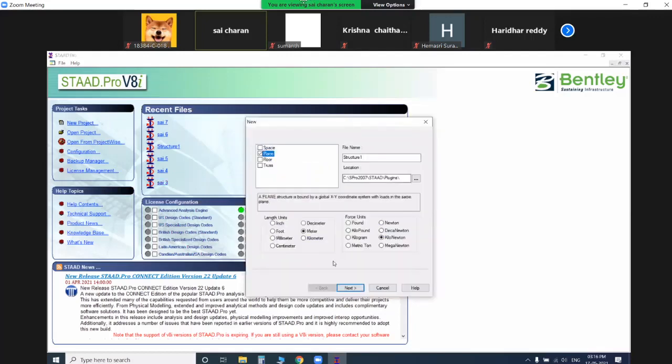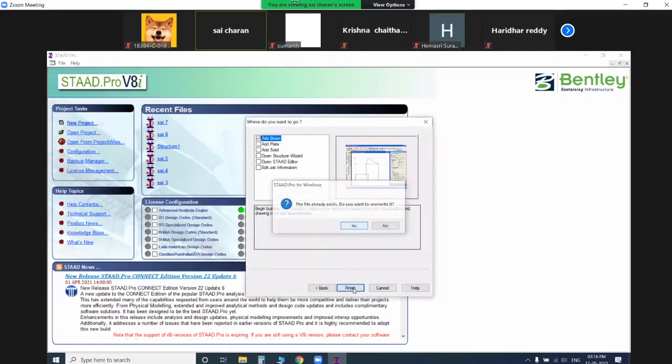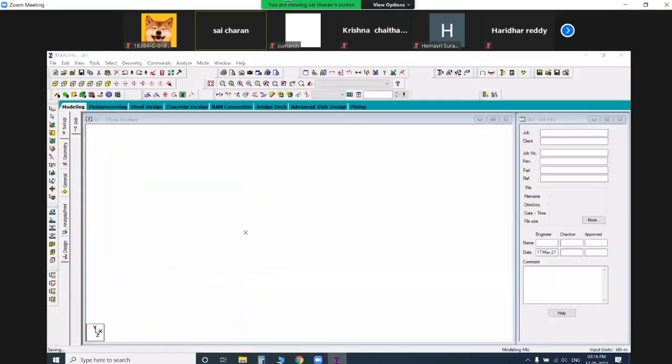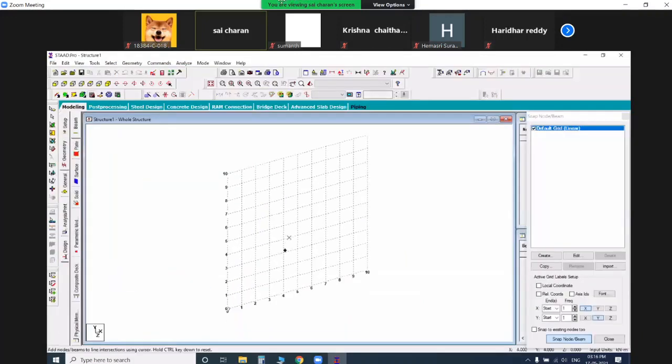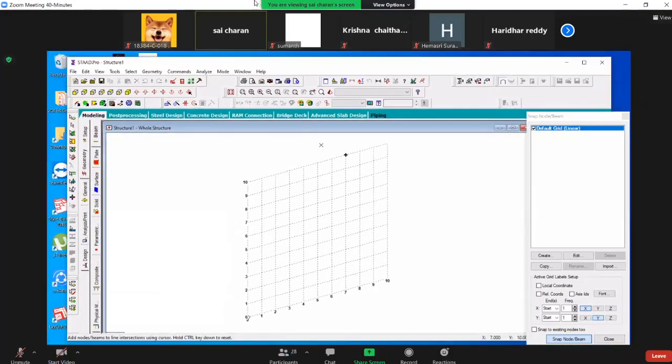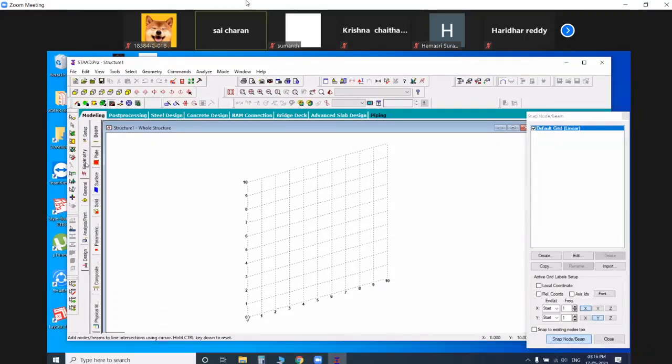First, open your software. Now, in this geometry box, we have 3 types of methods. One is the coordinate system, the second is the copy paste method, and the third is translational repeat. We have 3 procedures. These 3 procedures are geometry only, meaning step one of the procedure. These are the 3 steps. Now, I go with the coordinate method.